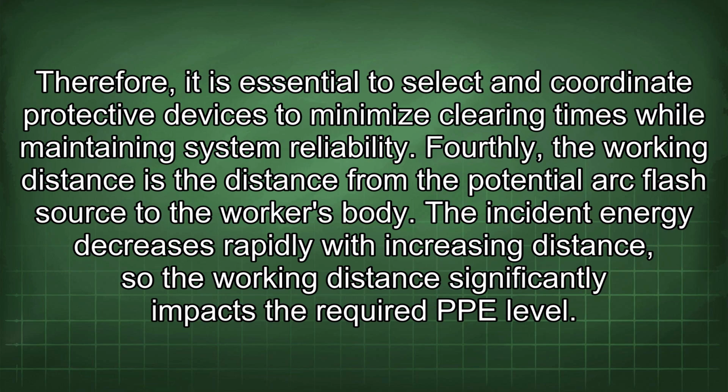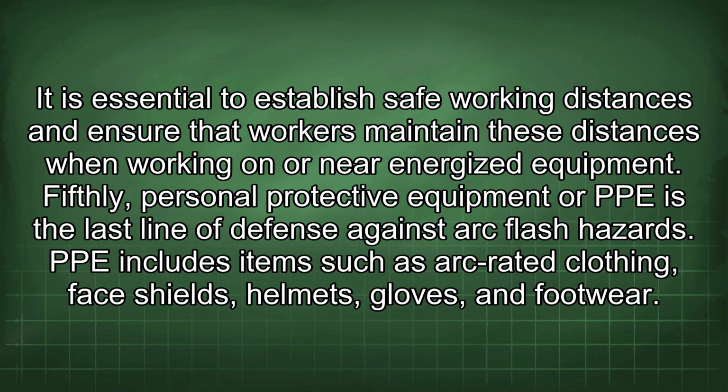Fourthly, the working distance is the distance from the potential arc flash source to the worker's body. The incident energy decreases rapidly with increasing distance, so the working distance significantly impacts the required PPE level. It is essential to establish safe working distances and ensure that workers maintain these distances when working on or near energized equipment.